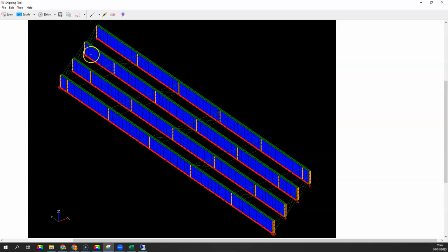It has skewed supports on both ends and it's got a lean-on bracing system here where we've got full cross frames with the diagonals, and we also have lean-on braces with just the bottom and top chords. If you are not familiar with lean-on bracing, this is a way to provide just enough system brace stiffness in order not to attract too much load in the cross frames in order to keep their sizes to reasonable dimensions. And there's other benefits like faster construction, reduced cost, easier inspection. There's tons of advantages to using lean-on bracing, especially for skewed bridges.